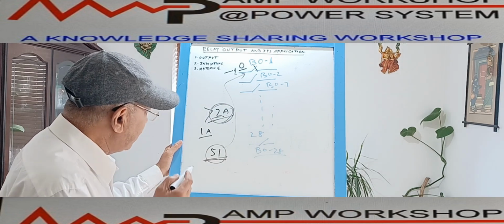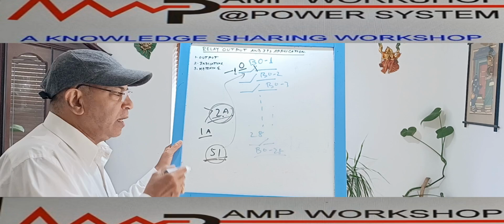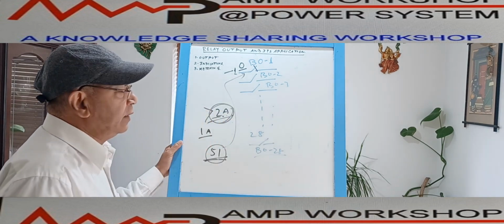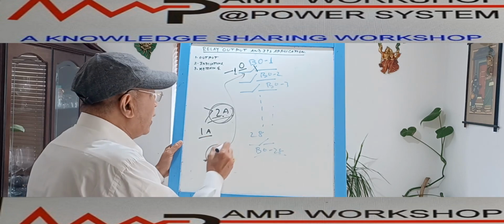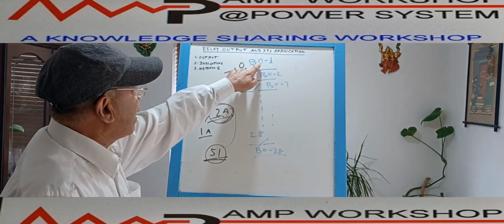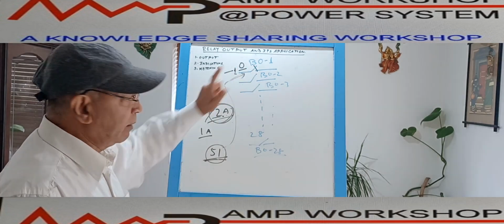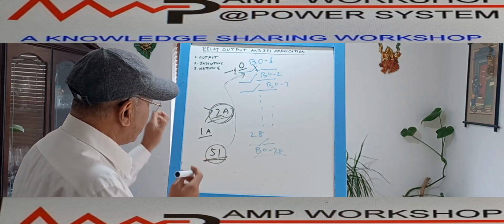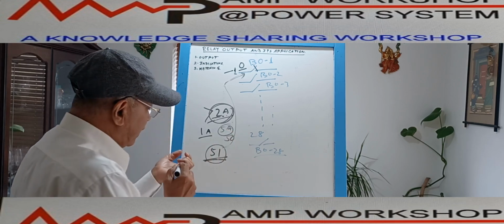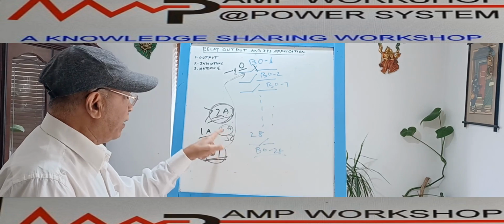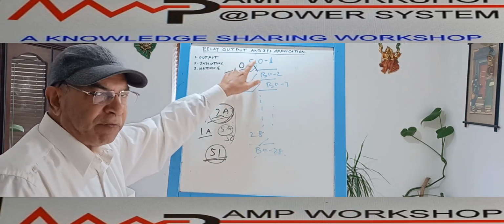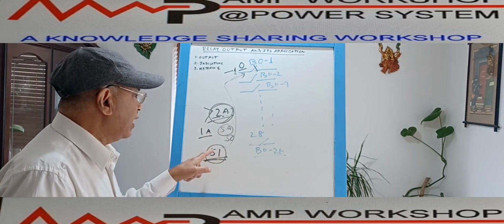When the current in the circuit crosses the overcurrent limit of 2 ampere, if we program that this condition immediately activates binary output 1, then the output contact will change over. Similarly, if it further crosses, say, 5 ampere, it will be considered as the instantaneous 50 function, and this output contact will also activate. So this binary output I can configure for both the 50 function as well as the 51 function.